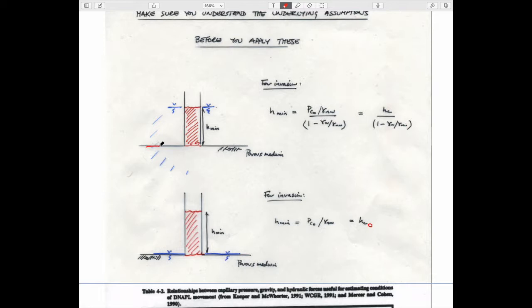And so the pressure that's acting on this interface is really the hydrostatic pressure due to this water. So you can think of it almost as the idea that in this case, the buoyant weight of this fluid is reduced because it's below water. It has buoyancy in it. And so the pressure that's acting here is reduced over the case where there isn't this water outside.